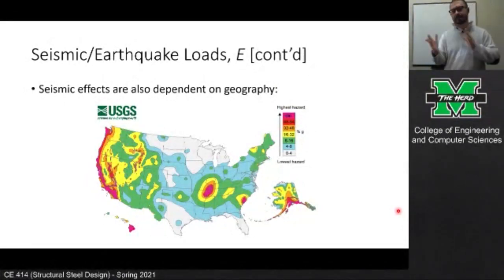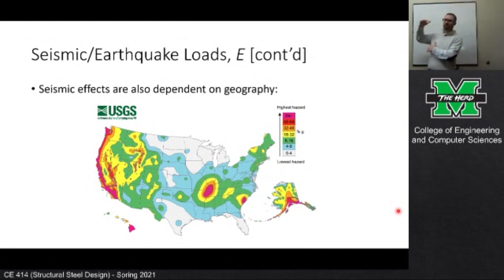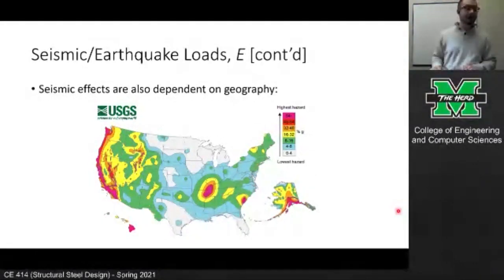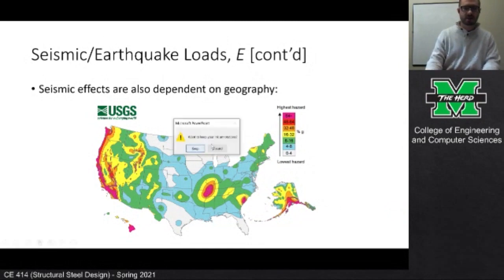Fortunately, this is where all the specs come into play. Based on your location, you can look up ground accelerations, and then through a series of adjustments and computing the weight of the building, you can come up with loads on the building and take it from there. But you really do have to roll up your sleeves and understand what you're doing.